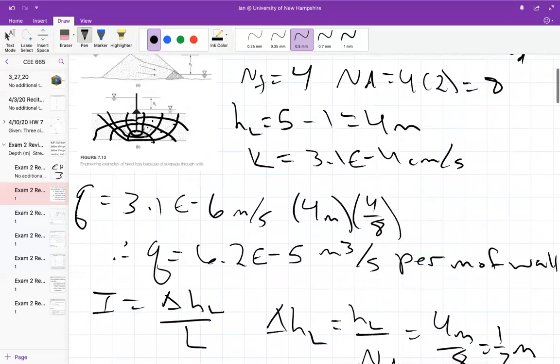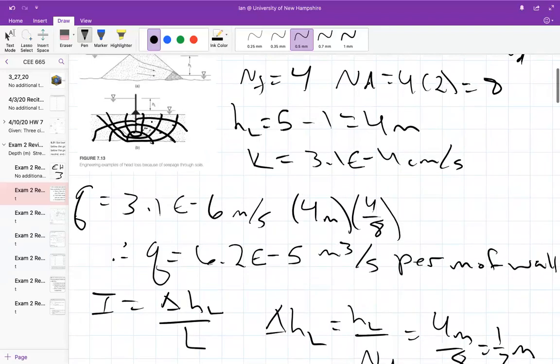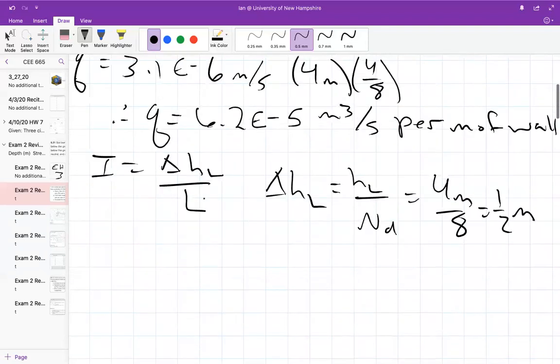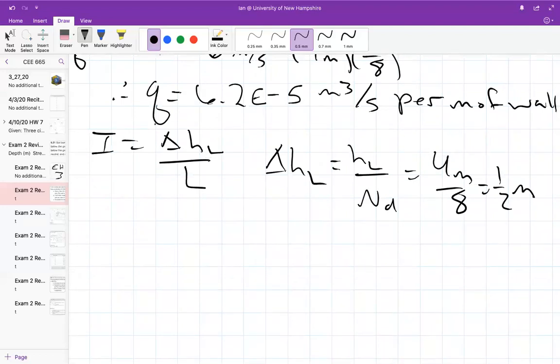If we were to draw this perfectly and scale it, we can measure it pretty finely and you would get a number: the distance L from the flow net, where L is the flow length in the first exit square immediately of the sheet pile. So if we were to scale this and do it real finely, we get L equals 2.375 meters.